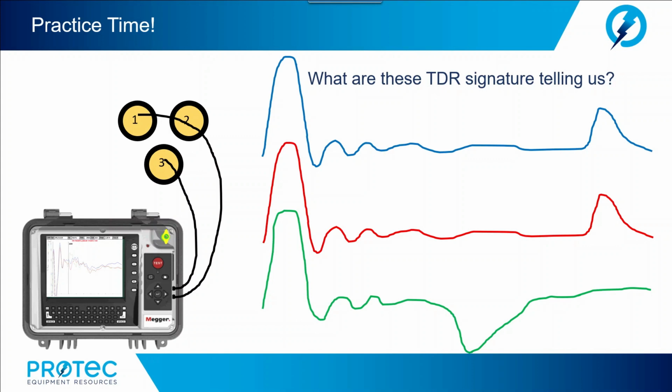All right. Well, when we connect between conductors 1 and 2, we see all the way to the end of the cable. When we connect between conductor 2 and 3, we see all the way to the end of the cable. When we connect between conductor 3 and conductor 1, we see a large decrease in impedance, or the pattern for a short circuit, and we never see to the end of the cable. The conclusion is that we have a short circuit, or conductor 3 is shorting out to conductor 1 at this location.